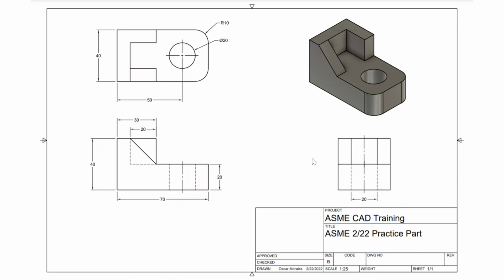Whenever you make these manufacturing drawings, the goal is to not have any repeating dimensions. So believe it or not, some things may be kind of hidden, but every dimension that you need to make this part is here. It might require a little bit of mental math to extrapolate some of the dimensions, but if you want to give a shot at this, we have 5 of us here that can come around and help.